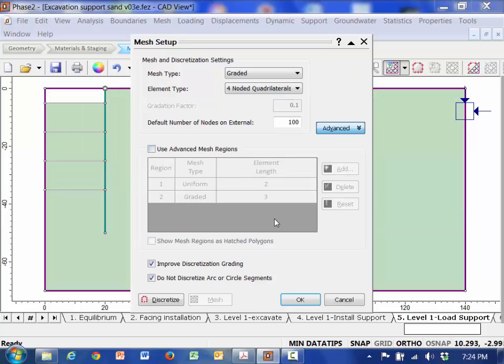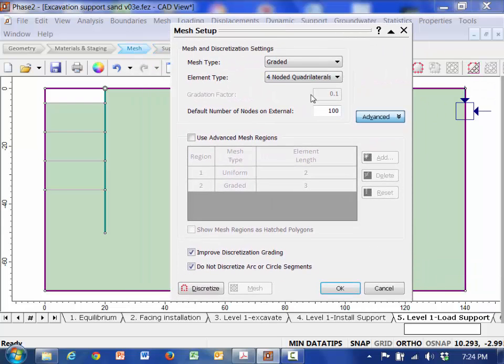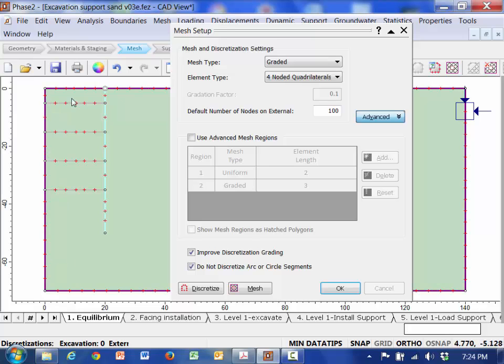All right. We're going to use quadrilaterals in this. Triangles don't work too well for continuum and stress. The quadrilaterals work a lot better. I'll initially guess about how many nodes we're going to want. I'm going to discretize this. And if you notice here, in this area, let me go back to the earlier one, we're only getting 2 nodes in each section. That's not very good.